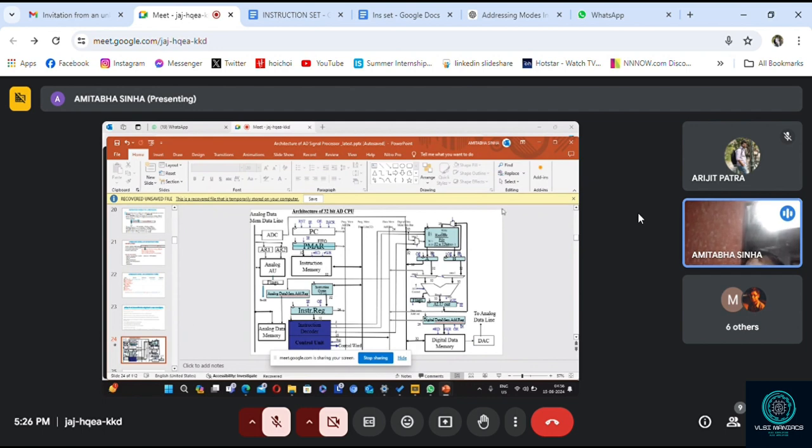Now, if it is a square wave, that means it's a periodic signal. And if the signal is periodic, according to Fourier series, it has an infinite number of sine and cosine harmonics and a DC component. So you take the higher harmonics from that, but the level will be very low. Then amplify that and filter out the other signals. In that way, the high frequencies are generated in the most modern VLSI circuits.